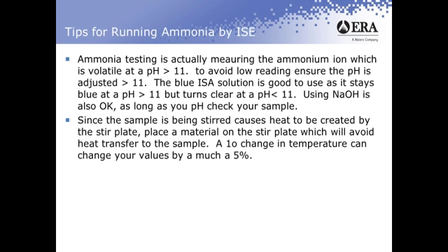So what I'd recommend, to prevent any heat transfer from the stir plate to the sample itself, is to place some kind of material on the stir plate which will prevent that heat transfer. Some cork board works real well. Packing material works real well. Something that'll trap that heat transfer. A 1 degree change in temperature can change your values by as much as 5%.